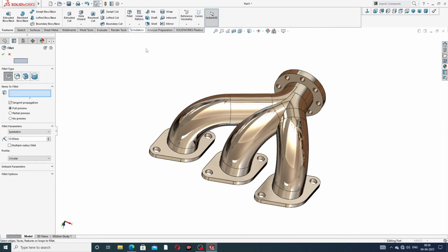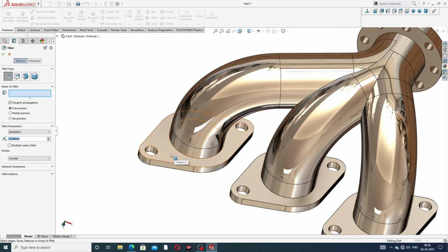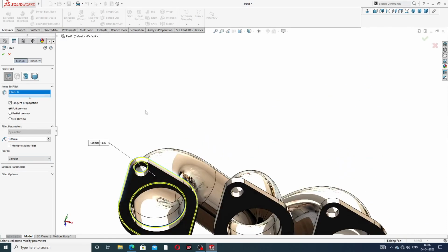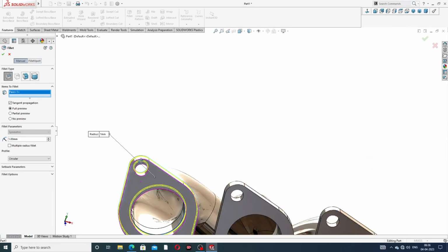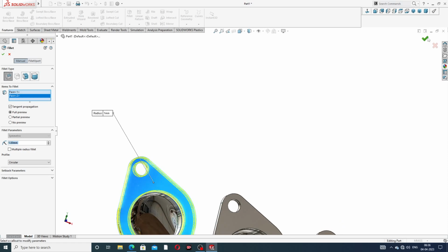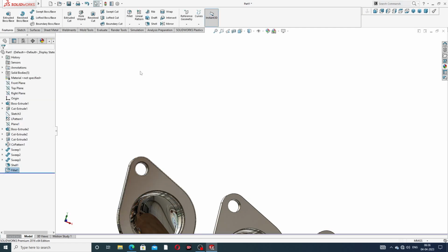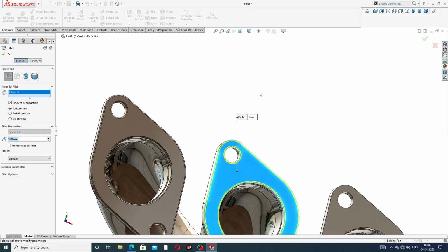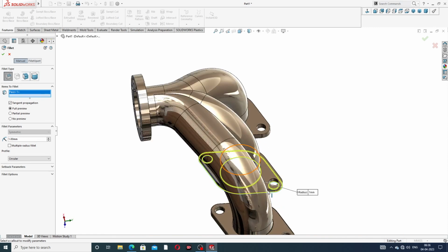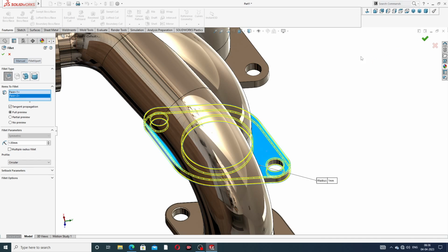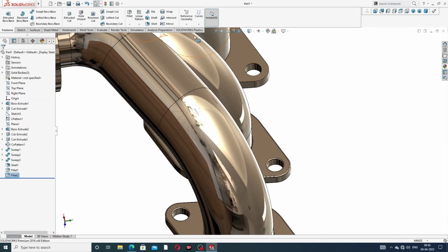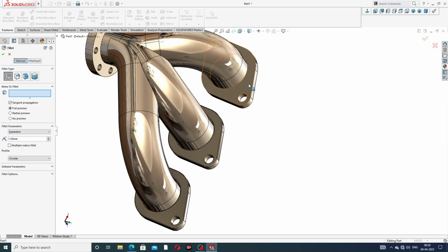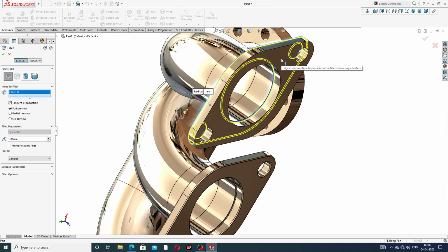And click a fillet of 1 millimeter on this sketch, and also the back side, select this, click OK, and again select a fillet, use this to this, click OK. And again select a fillet from this to the back side, select OK.